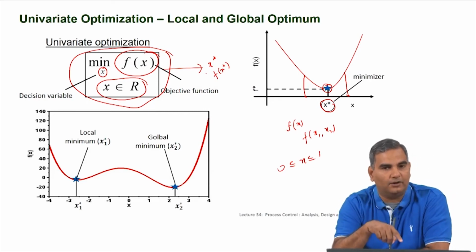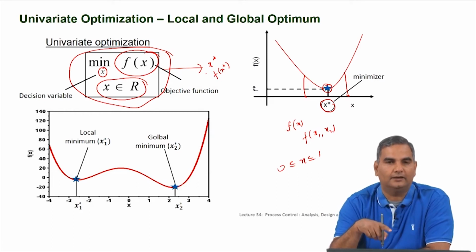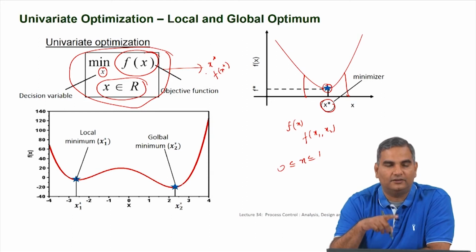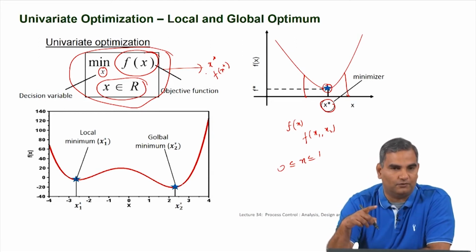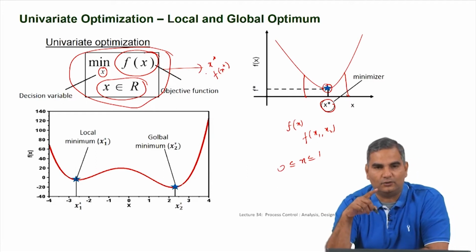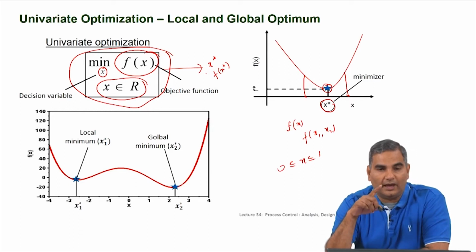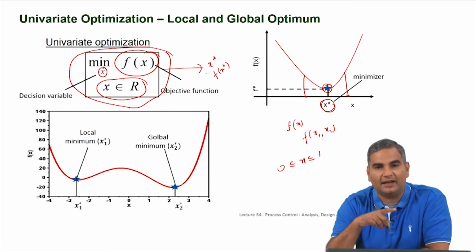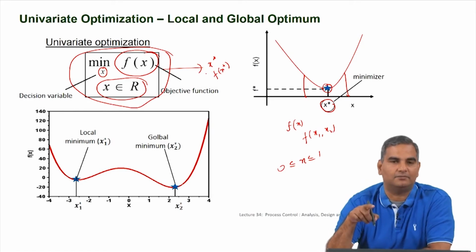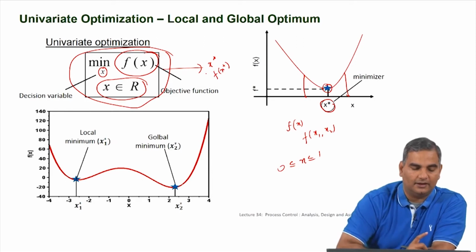So, this is very important to remember, because when I connect this to control, we are going to write the optimization problem with decision variables which are the move plans, right, the choice for the input values that we talked about. So, I have uk plus 1 all the way up to uk plus m minus 1. So, those m variables, if I can find values for that such that some objective is optimized, then I have my move plan. So, that is the connection between control, model predictive control and optimization. This is something that you should keep in mind.